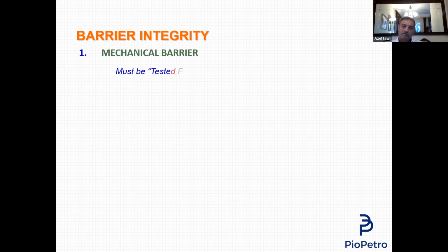Here comes the answer. Direction of flow. Please don't tell me from below or from top or from the side. It is from the direction of flow, regardless of where the flow comes from. Normally when we work in the oil field, in the wells, pressure comes from below. So it doesn't make any sense that you have a blind ram on a BOP, you need to test it, you close it, and now you test it from above.